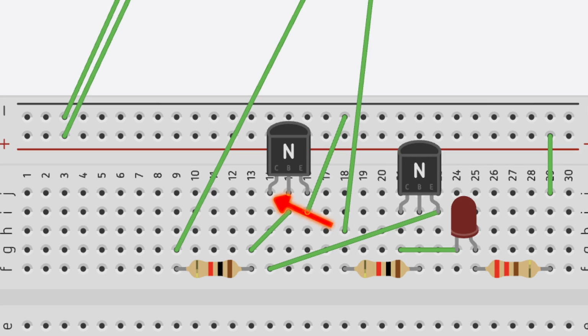Now we bring a resistor down from pin 10, pin 11, it's from pin 11. So in the C code we'll be able to turn this on. And then we put a piece of wire here to go from the end of the resistor over to the base. Now the emitter here on the second transistor goes to ground.